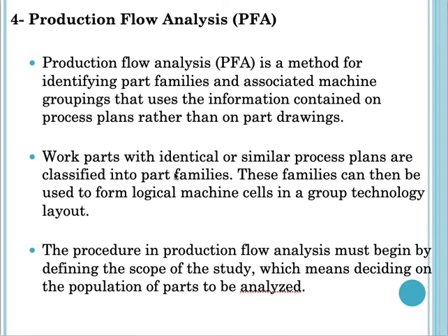Work parts with identical or similar process plans are classified into part families. These families can then be used to form logical machine cells in a group technology layout.